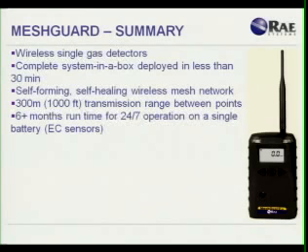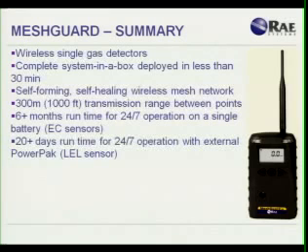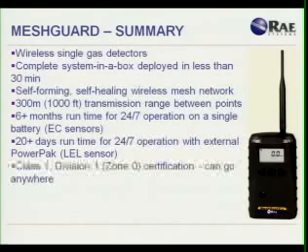We have 6 months runtime for true 24/7 operation. So this is on all of our electrochemical sensors. For the LEL sensor, it's really more of a power consumption issue. To get accurate readings, you need a lot more power running through an LEL sensor. So we have an external battery pack that runs 20 days. We're going to talk a little bit more about that, we have a solar option with it. So currently the power pack lasts 20 days with the LEL sensors.